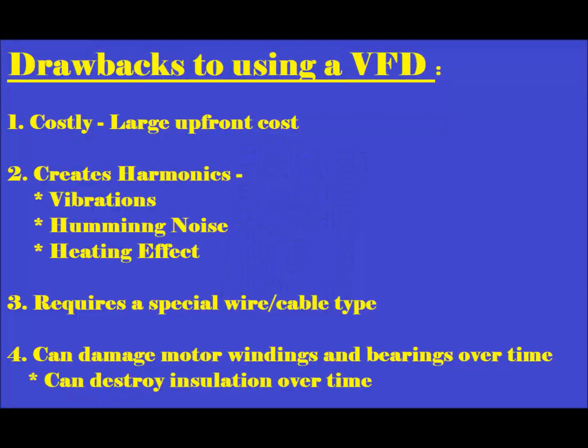Next we'll come to the drawbacks or disadvantages of using VFD. First point is it is very costly as compared to any other switchgear. Second, it creates harmonics which result in vibration, humming, noise and heating effect. Third point, it requires a special type of cable or wire. And fourth point, not being that important, it can damage motor winding and bearing over a period of time, and can also destroy insulation over a period of time.